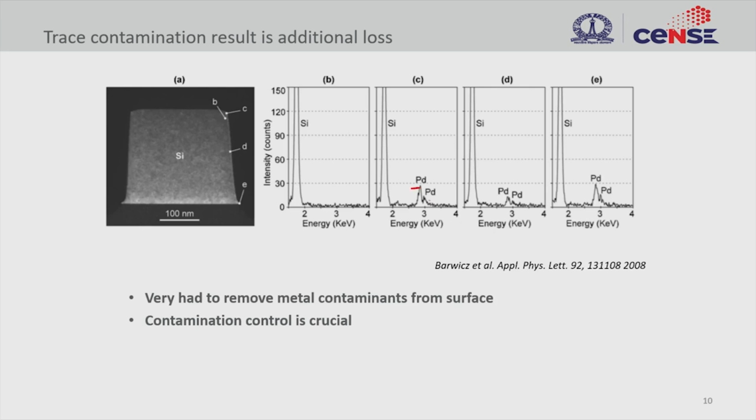If you expose your substrate to any kind of beakers or any vessels that you use in order to clean this material, then the contamination on that particular glassware will come and sit on this substrate, and you're going to find it difficult to remove it. And this can be very specific to the position on the wafer or position on the structure itself.